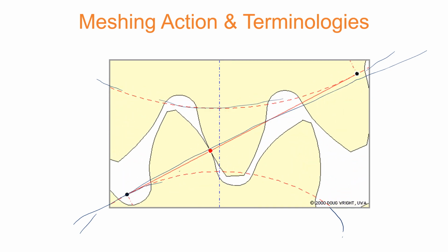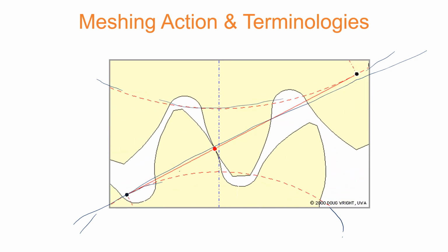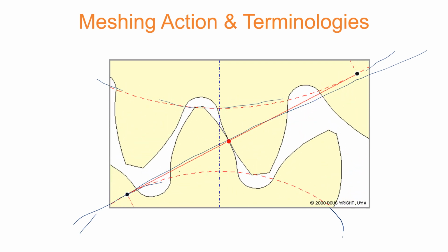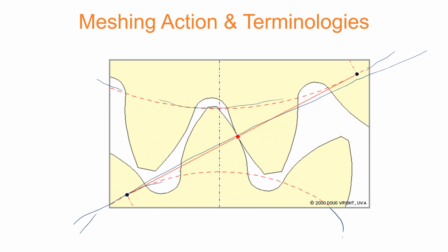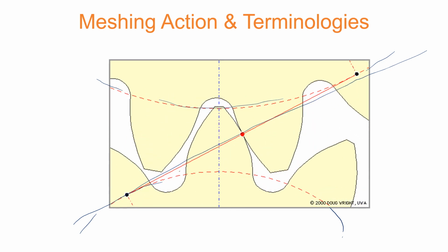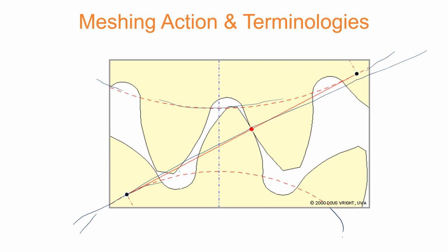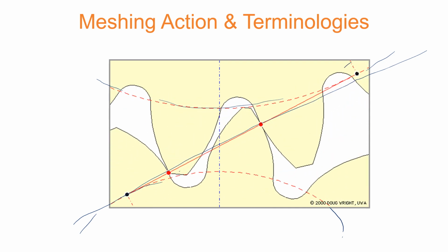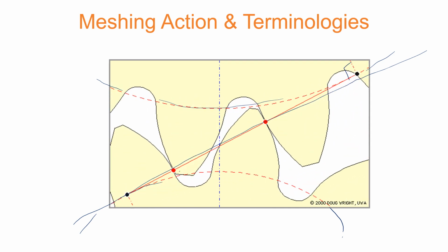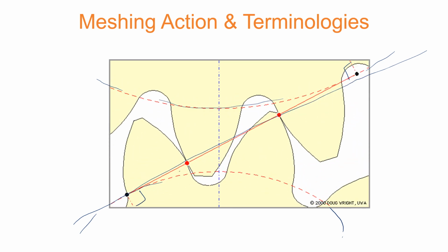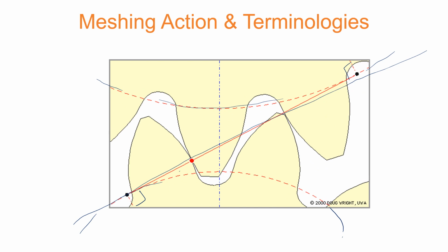We're going to further elaborate that later on, but at this particular stage you need to realize that the involute curve profile that I mentioned in the previous slide is the profile followed over here. And this follows a straight line, which eventually is going to be at 90 degrees to the base circle for the input side and 90 degrees over here to the base circle of the output side.